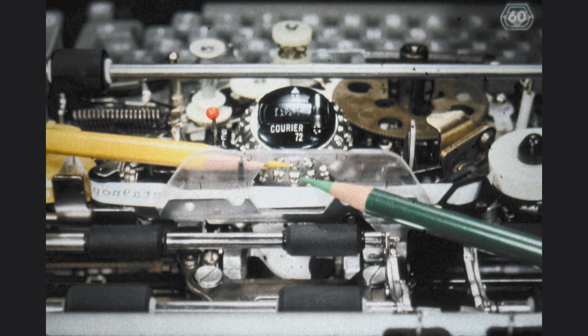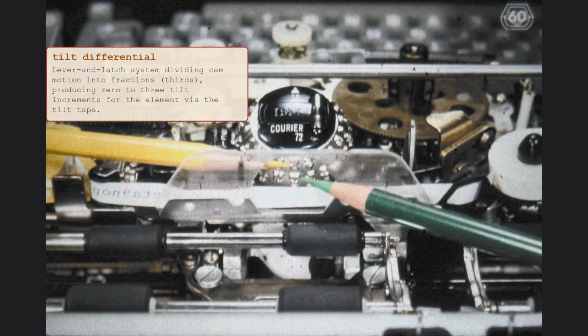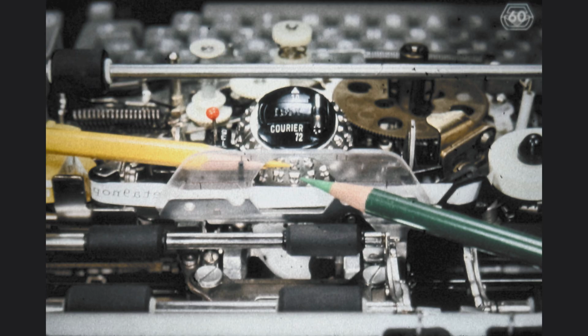The motion for all of the tilt action is furnished by a mechanism called the tilt differential. These various amounts of motion are transmitted to the element by the tilt tape system, which we will study in just a minute. Let us repeat that the tilt motion which causes the element to rotate from Z, a tilt 0 character, to J, a tilt 3 character, is powered by the motor, so we say the action is positive. The restoring of the element from the tilt 3 position, the position in which it printed J, back to tilt 0, at which the element would print Z, is accomplished negatively, through the action of the tilt spring.